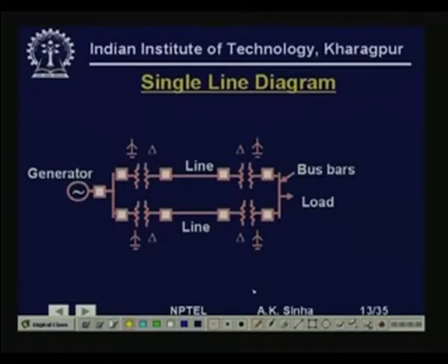And now I will show you how we build a single line diagram using these symbols. Here we have taken an example of a three phase generator connected by means of two step up transformers to a double circuit transmission line, then through two step down transformers to a low voltage bus bar to which load is connected. So, we have used the generator symbol here, then we have a circuit breaker for protection of the generator, connects it to a bus bar shown here.